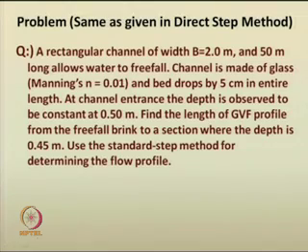The problem you have done for the direct step method. In the direct step method, we had given you the same problem, if you recall. We had suggested a rectangular channel of width 2 meter and 50 meter long allows water to free fall. The channel is made of glass and the bed drops by 5 centimeter in the entire length. So, at the channel entrance, the depth is observed to be 0.5 meter.